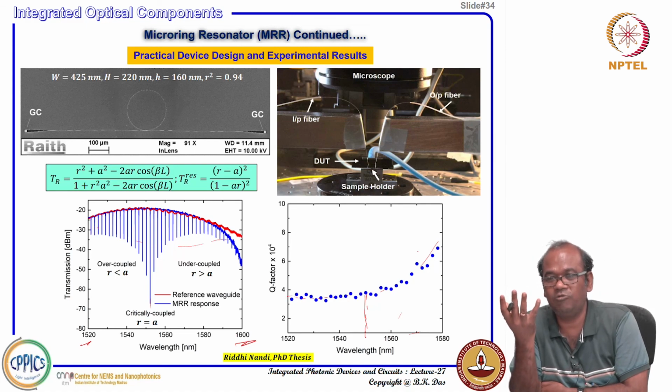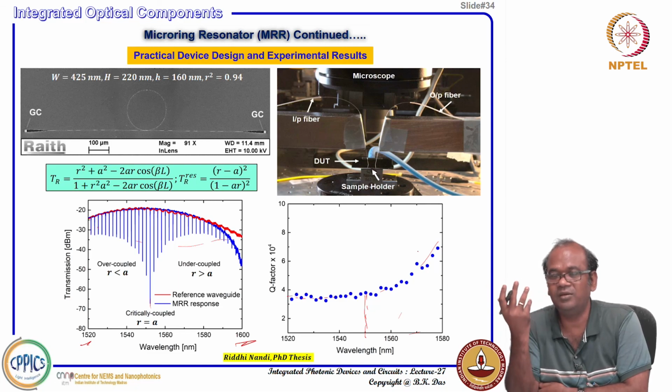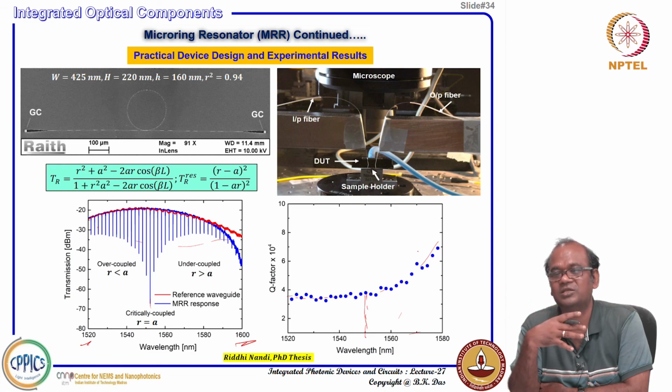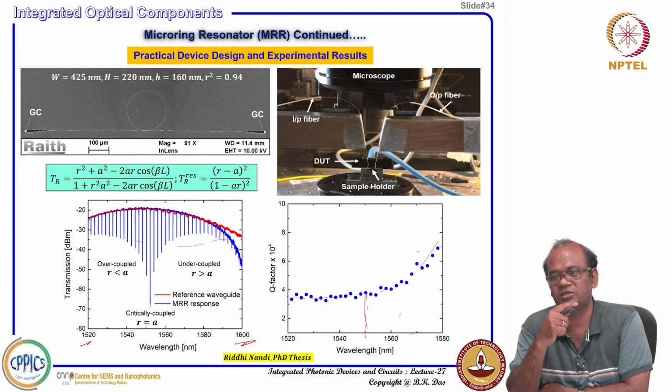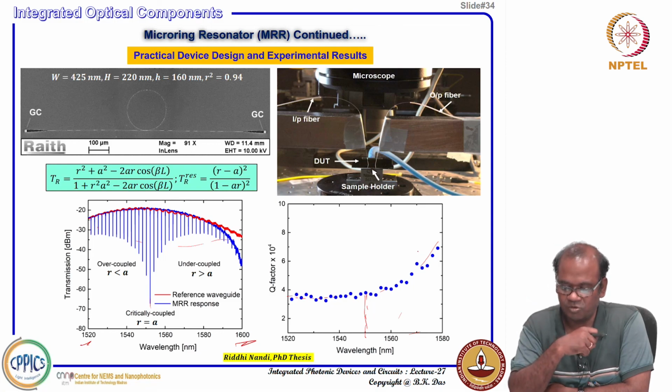Q value is required. Q value is highly dependent on the waveguide loss, the perimeter length, the volume of the cavity, etc. And depending on that, we can think of various types of applications. This ring resonator is heavily used for photonic integrated circuits. Two devices, the Mach Zehnder interferometer and the ring resonator, are heavily used, and both of them are designed with a directional coupler. So, we have discussed the microring resonator and the Mach Zehnder interferometer, and probably in one more lecture